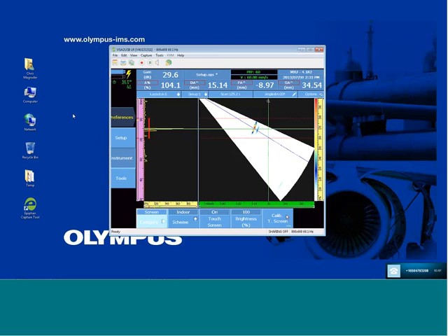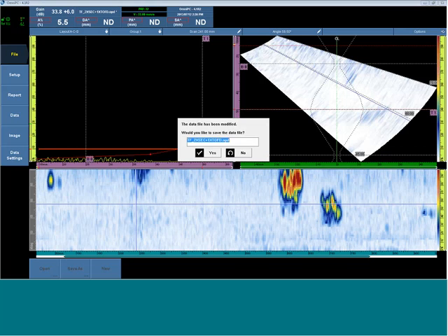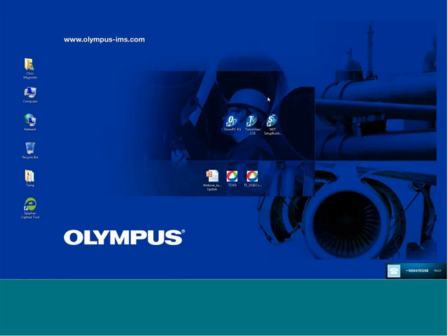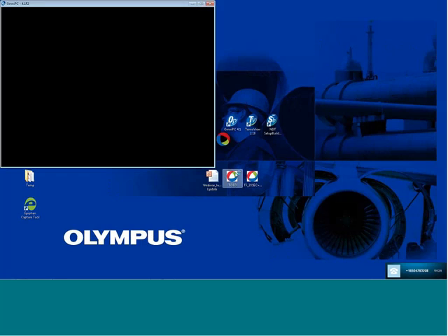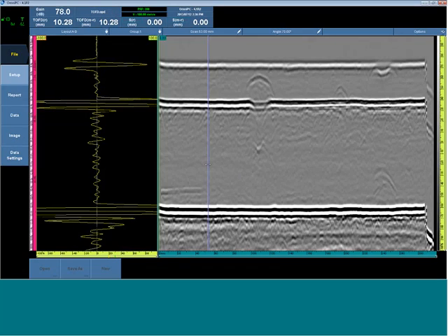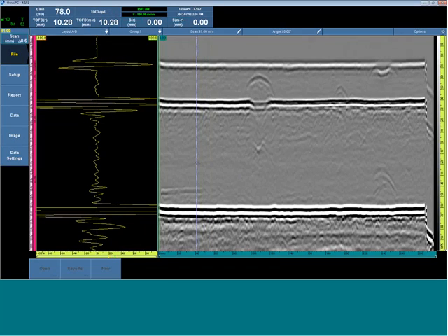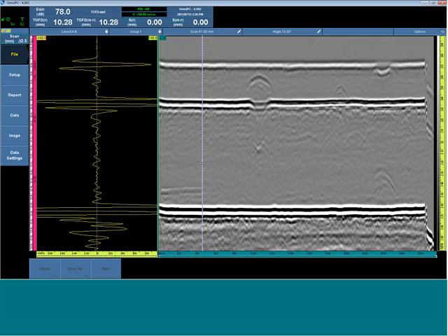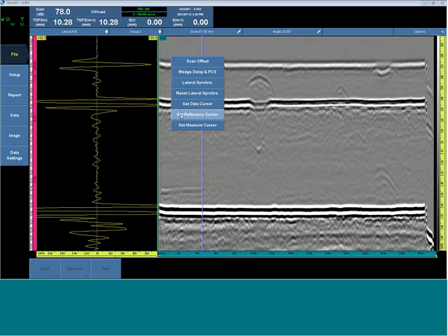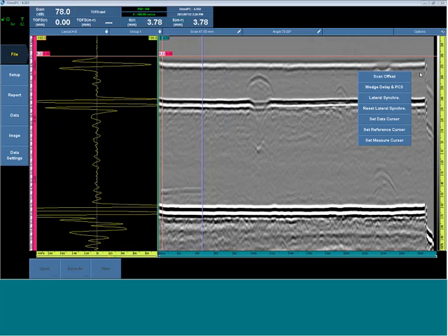I want to tell the software for each A-scan where the lateral wave starts and the area that completely contains it. Prior to lateral wave synchronization, good practice is to ensure no flaws are directly in the lateral wave and synchronize. So that will straighten my lateral wave significantly and allow me to perform a wedge delay and PCS calibration.